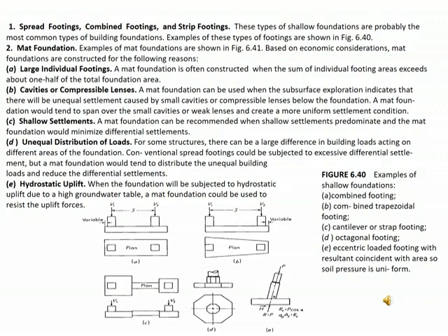And E, hydrostatic uplift. When the foundation will be subjected to hydrostatic uplift due to a high groundwater table, a mat foundation could be used to resist the uplift force. So this is for the kinds of footing and foundation. Depending on the conditions, we have to utilize the appropriate kind of foundation.